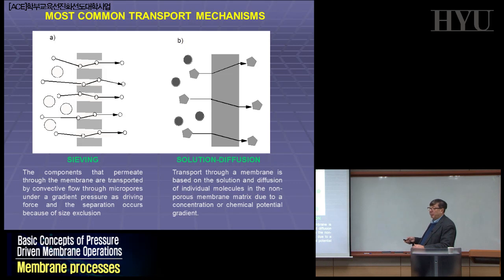That can be, for example, a material such as cellulose acetate, very hydrophilic, in which water molecules can have very high solubility. Other species, salt for example, or any other chemicals, have no solubility at all, or very, very low, in this kind of system. So these species will dissolve initially, and Henry's law will control solubility, in principle, in the ideal case.